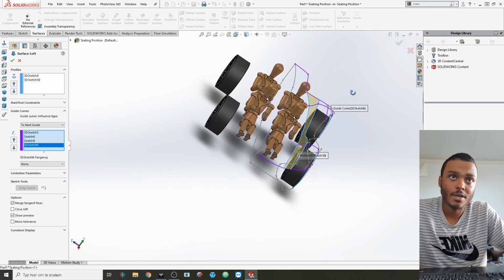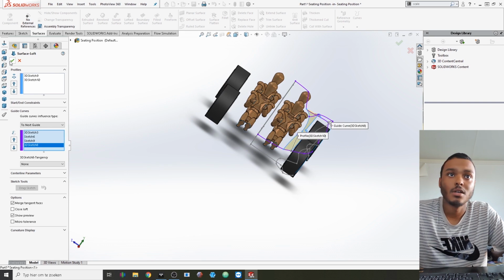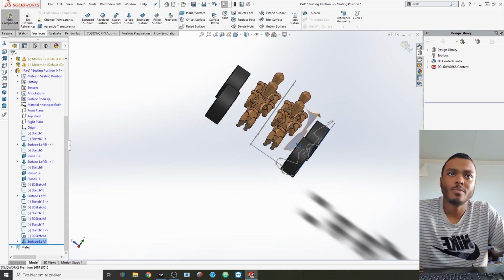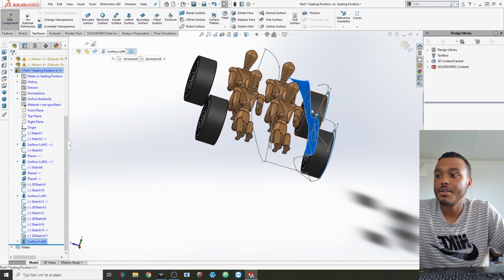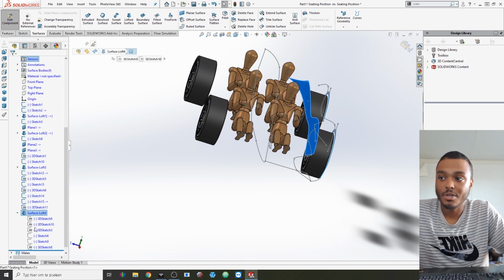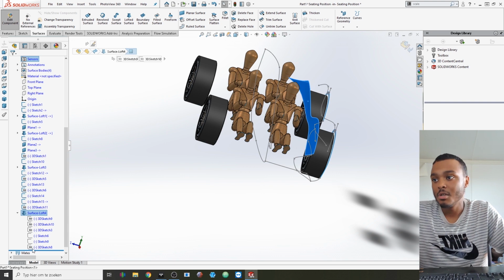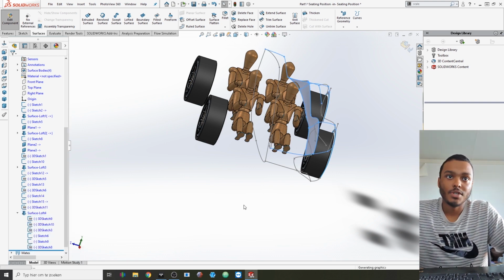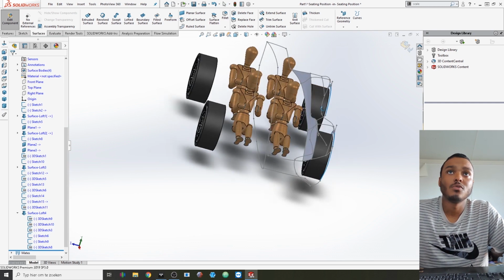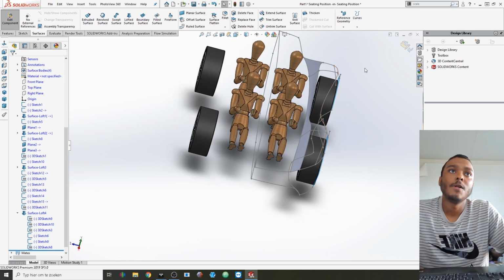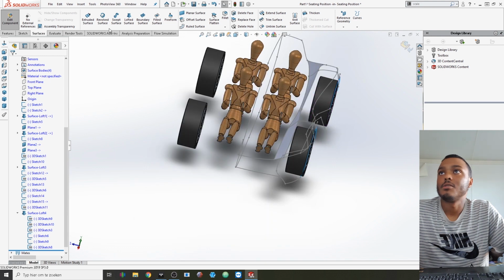But right now in my case, it's showing that it's going straight, as it's supposed to. You can also see that once you've used a couple of sketches in a guide curve like that, it takes away all of those sketches and hides them. So you do that to showcase all of them again, and then they will stay in there so that you can use them over and over again. That is also something that I always do.